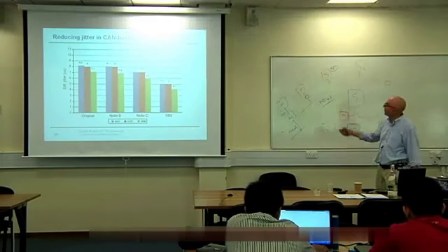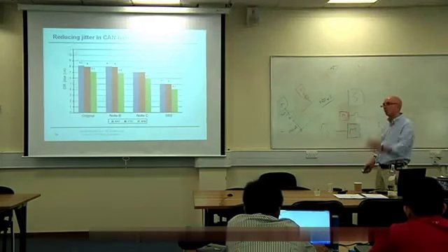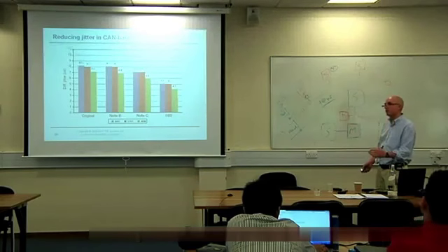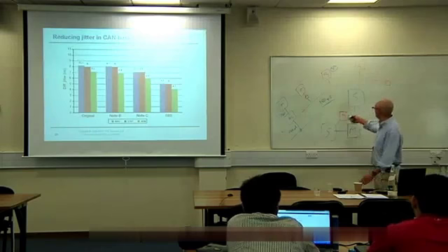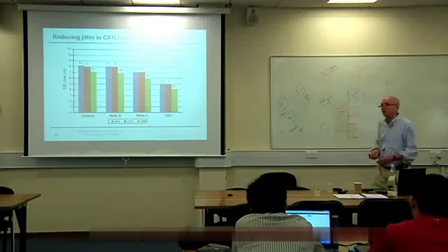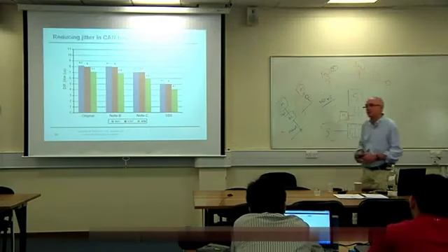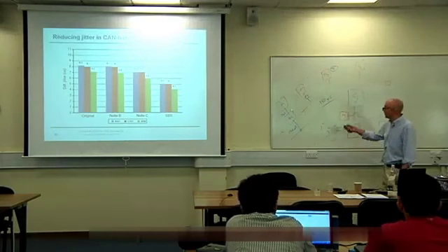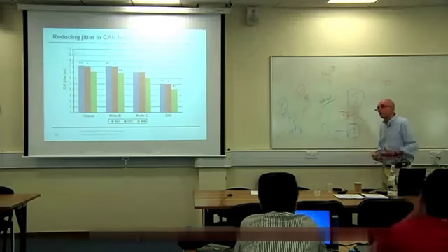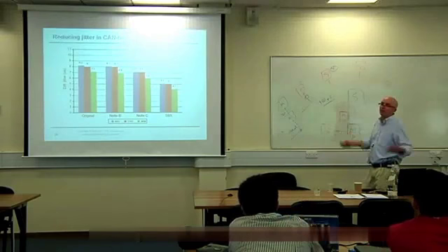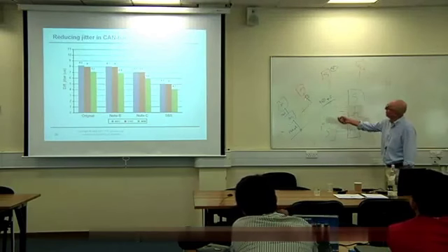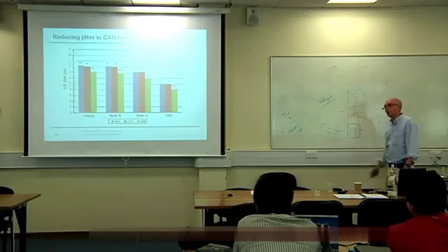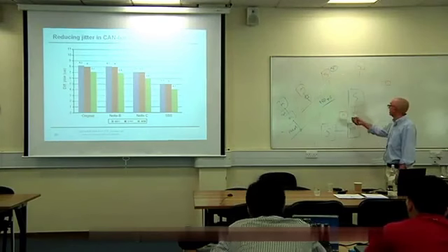So what you can do then is just have the master forming the heartbeat of the network, and all of the other data communications happening according to a slightly revised protocol through the slave. But you still have the advantage of doing the shared clock design. Again, it's no perfect solution. This effectively makes this a redundant node that's just doing the timekeeping, and all the processing is then done by